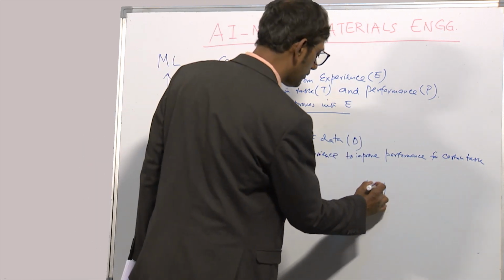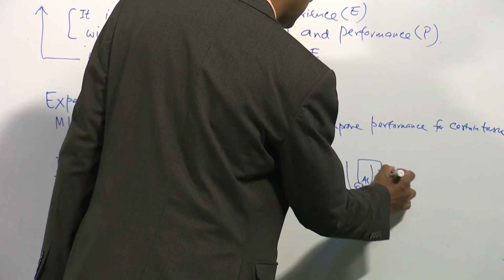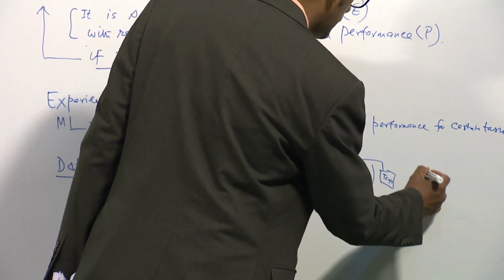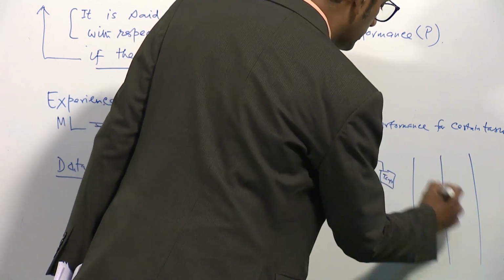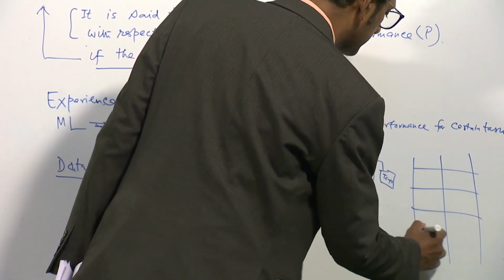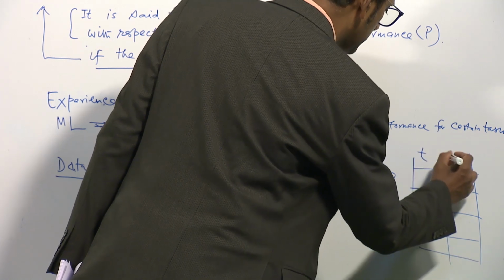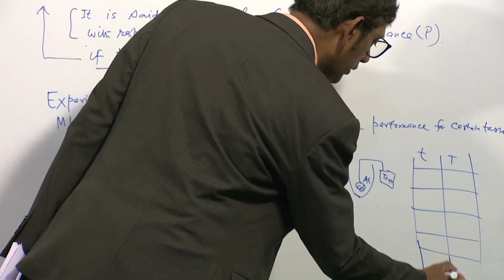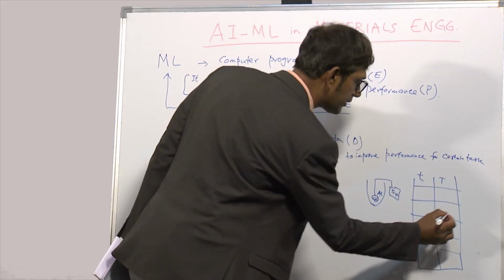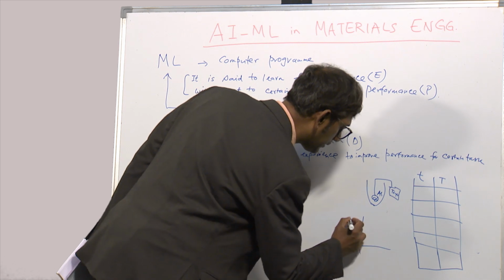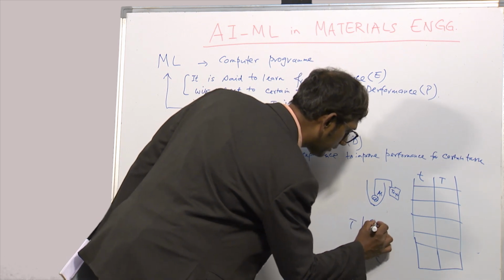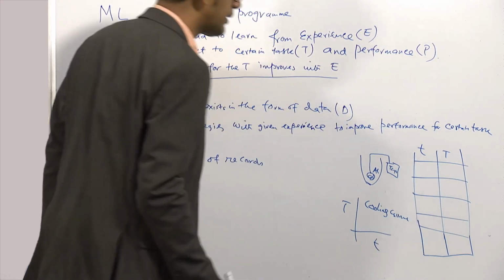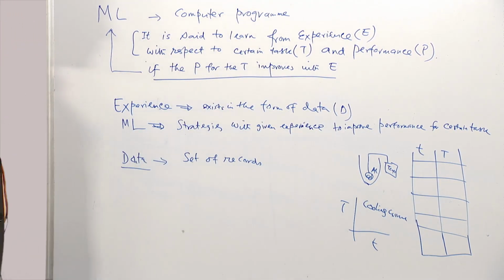Then you put a thermocouple connected with a temperature device, and you list down temperature as a function of time, as the liquid aluminum is cooling down. This is what is used to plot temperature versus time, or the cooling curve, right?